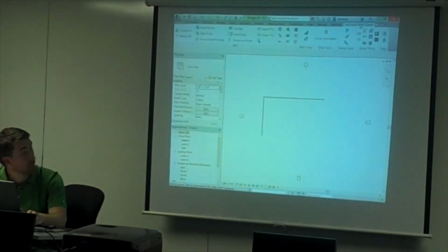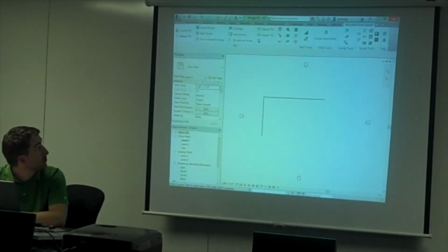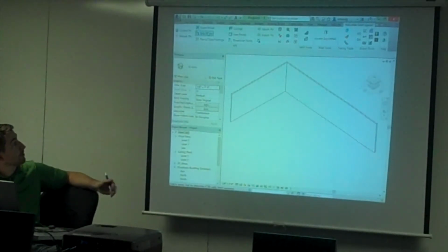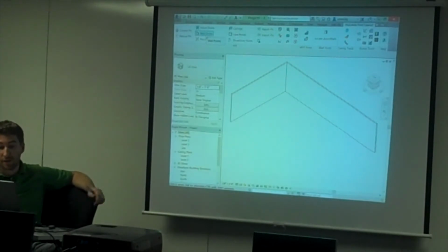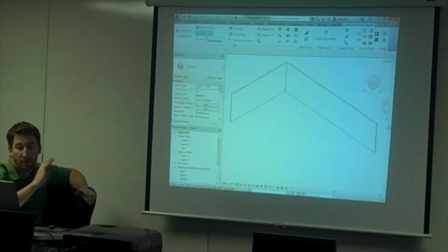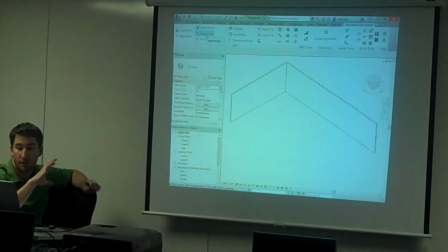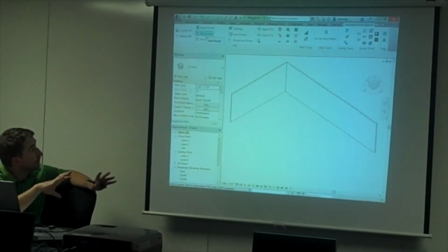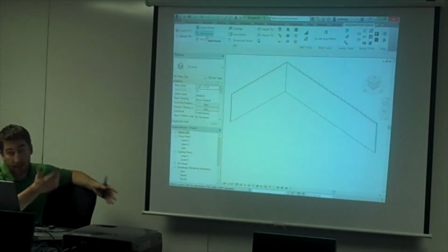So you'll notice that I've got the point layout module loaded up inside of Revit. And so what you can do, let's turn to a 3D view for example, you've got the opportunity to create points off of a lot of different features. So probably the first way that you might use it is, again, you've got a 3D BIM model already, and you want to go ahead and turn these points into something that they can take out into the field.